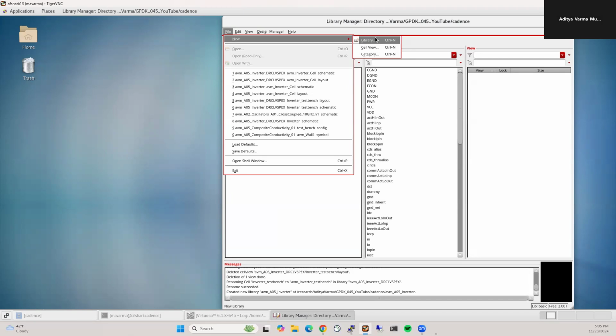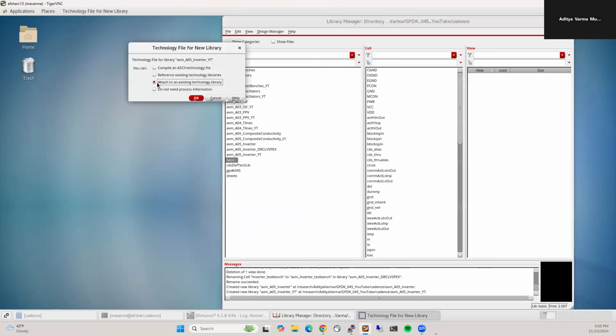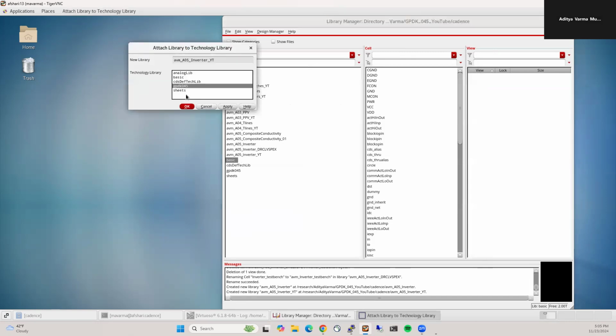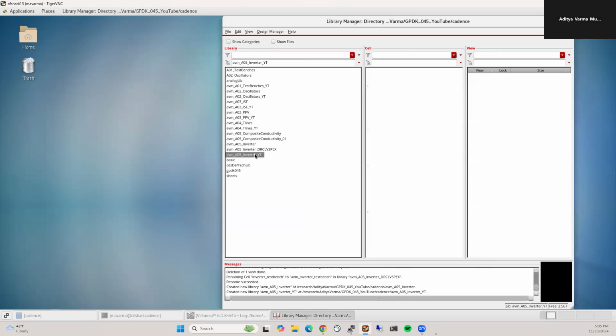Okay, so I'll create a new library. I'm going to call it AVM A05 inverter YouTube. And as I mentioned before, when you're making a new library, always use some kind of initials. For me, it's AVM for my name, so that you can differentiate and it makes collaboration much easier. Okay, so I'll say attached to an existing technology, attached to GPDK, hit OK. And that's the new library.